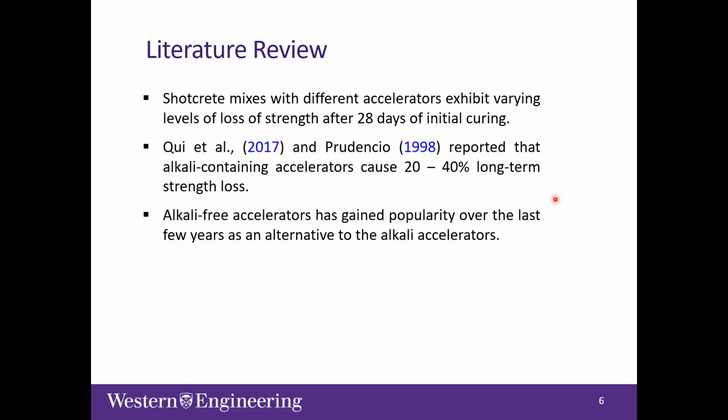Despite this advantage of the early strength, shotcrete mixes still exhibit varying levels of loss of compressive strength, especially at 28 days after curing. Several researchers reported that especially the alkali accelerator, the sodium silicate one, loses between 20 to 40% of its strength. This leads to the widespread popularity of the alkali-free accelerator as an alternative. However, the alkali-free accelerator still has its own disadvantages, such as the high cost.